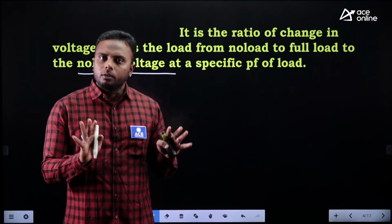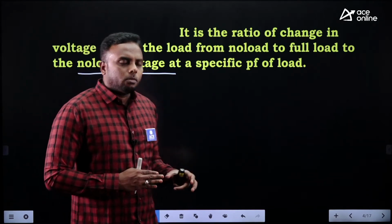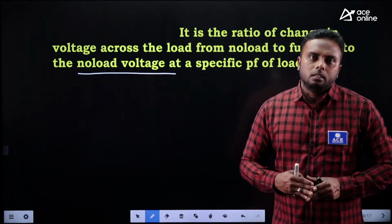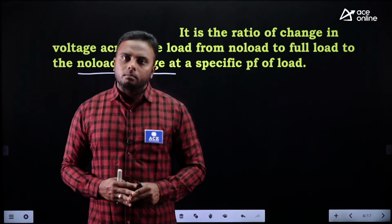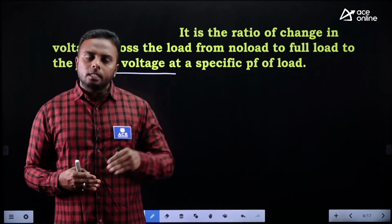Some 5 to 10 volts will be dropped approximately. In a practical transformer, the maximum regulation will be around 4 to 5%. Take 5% also: 5% of 200 means some 10 volts will drop, maximum. Generally 4 volts, 5 volts, 6 volts, those fluctuations will be there.